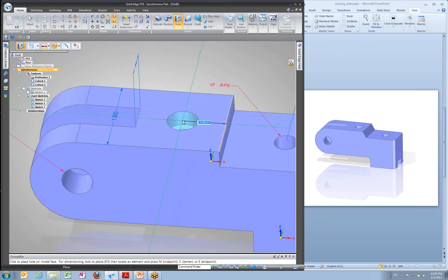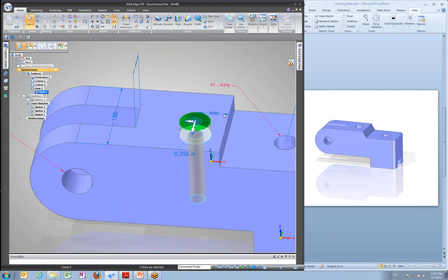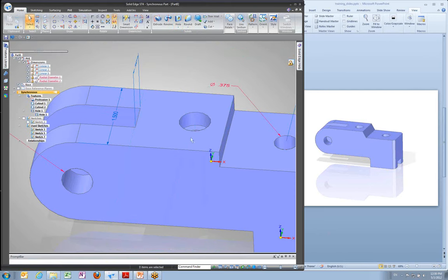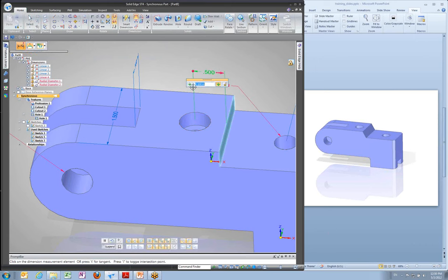So now I can snap it so it's at the middle, and then key in, let's say, 0.5, and then hit Tab as my dimension. And what that's going to do is position it exactly 0.5 inches from that edge. So that's one way you can place it on the fly. The other option is just to drop it in there and then place a dimension after the fact. There's no right or wrong way. Personally, I like dropping it anywhere and then using the steering wheel or dimension to place that with some precision. Just remember when you place your dimensions to make sure that you're adjusting the right side.